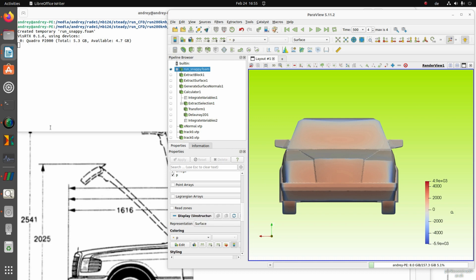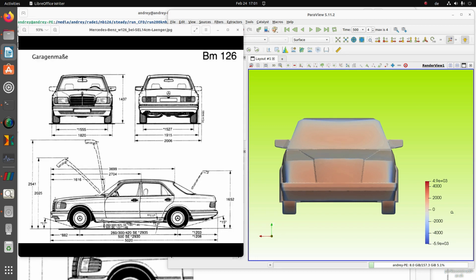And now we can proudly discuss the summary. The first thing that we looked at was the mesh. Then we prepared the system files from 0 folder, constant to system folder. As a second last step, we looked at the results, like cutting plane, streamlines, wall-bounded streamlines. And finally, we calculated the drag force, the power to counteract the aerodynamic drag, and the drag coefficient. And now we have reached the end.